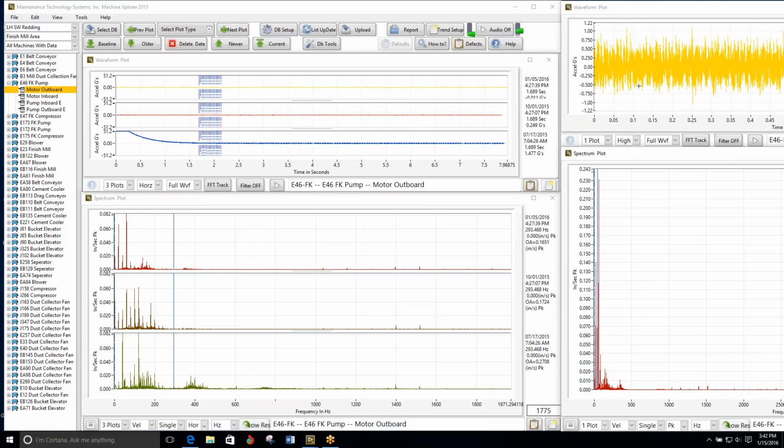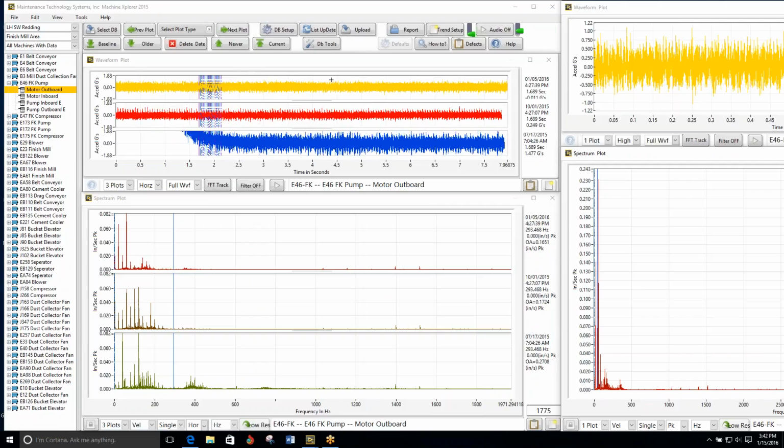So over on the right-hand side here, I've got the worst case out of those three pieces of data. On the left-hand plots, I get a little bit of history from those guys. All right. In this case, it's basically 6 months of history because we go out there once every 3 months. Looks like they did something to it between the first and second one. Possibly, or just differences in load or temperature or whatever. So where it's still less than 2 Gs, it becomes a who cares, and even though there's a little bit of difference there, we just keep going forward.